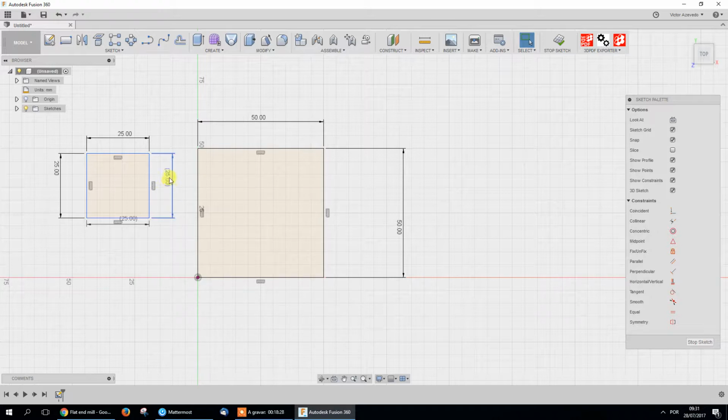Other thing that happens here is you have brackets on this measurement and this one. This is a driven measurement. What it means is that something else is locking already the design and you can't change that one. And it just tells you it's this size and you can't touch it. Okay? That's why it's on brackets and you can't change. You can double click and it won't matter. This you can double click and say 26 and change. Back to 25, enter, and it's okay.